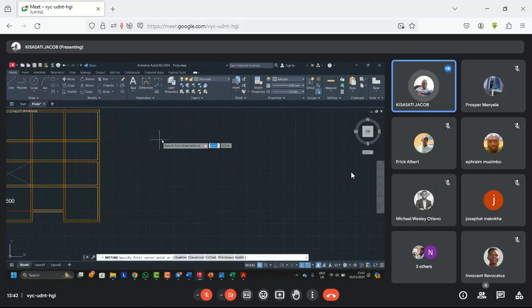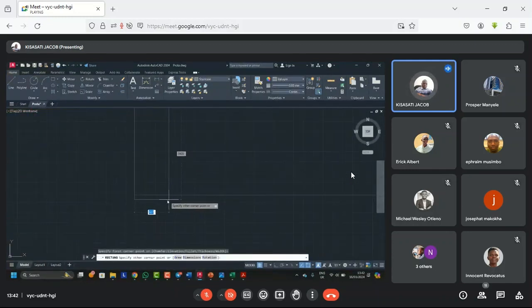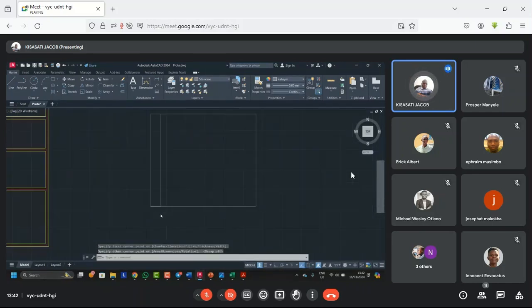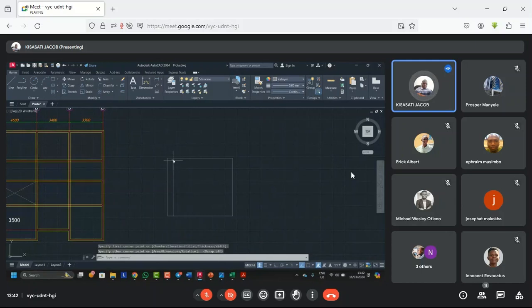What about the case of the cantilever slab? We can just have this slab, of course. Then this is now the beam. Assuming that this is the beam, we have a column here, we have a column here. Then this one is now a cantilever slab supported on one side only. Because the slab has four edges, we have this one, this one, this one, this one. So supported on one edge, that is a cantilever slab.